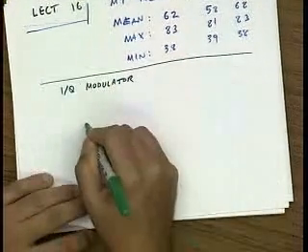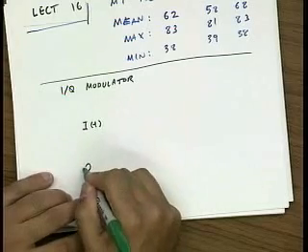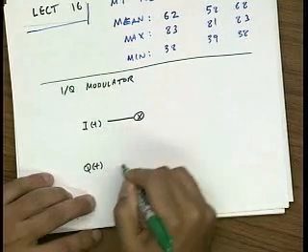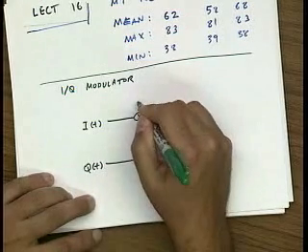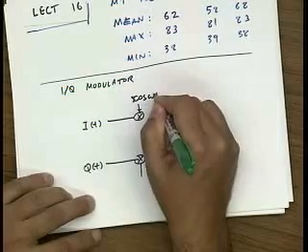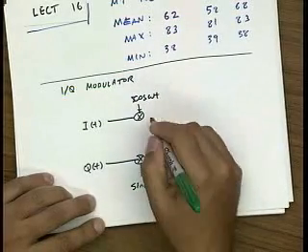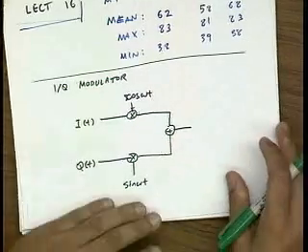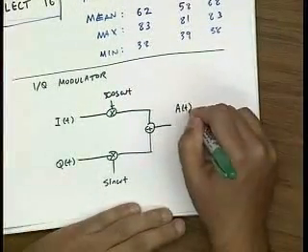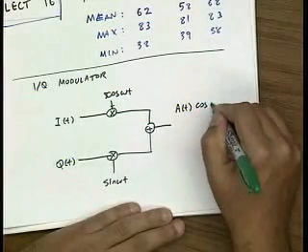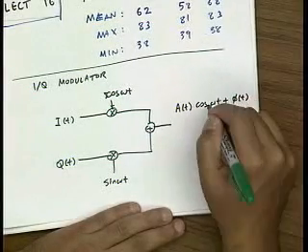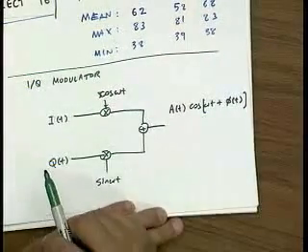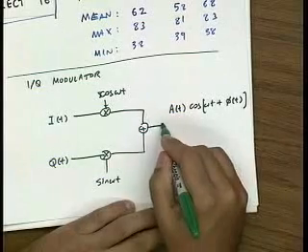And the idea was that if we had two signals, I of t and Q of t, which are signals as a function of time, and we multiply these by, let's say, sine and cosine, and we take the sum, we showed last lecture that this sum signal has an amplitude and a phase, which basically allows us to use this one dual mixer configuration to do amplitude modulation and phase modulation.